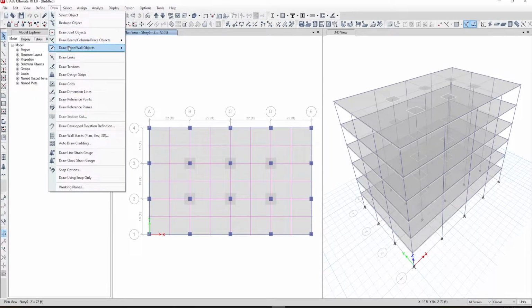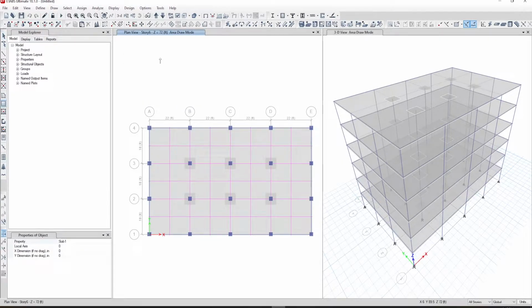Click the rectangular floor tool. Change the object property to opening in the drop-down list. Ensure that the snap to grid intersection and point command is active. This will assist in accurately drawing the shell object. This command is active when its associated button is depressed.